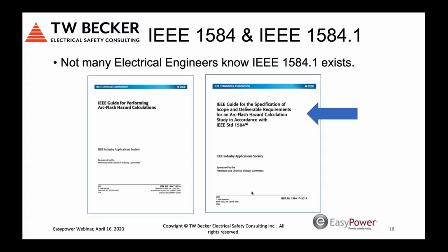So I would encourage you to buy IEEE 1584.1 if you are completing arc flash hazard incident energy analysis studies and calculating the arc flash boundary, because it will allow you to do a gap analysis to how you've been doing those studies, and specifically the reports issued. And I have been reviewing some of these reports for my clients, and there are significant concerns I have at times with respect to the content and the quality of the reports.